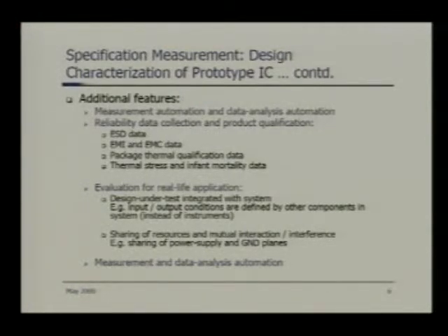Other than that, we have to qualify the IC, say the amplifier, for real life application. When you are talking about characterization of a particular amplifier, putting it on the PCB and connecting it to the RF signal source and RF spectrum analyzer, we are not putting the circuitry in a real life scenario.